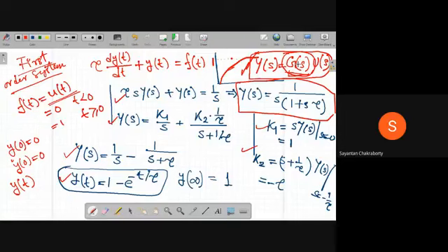So obviously this Ys will have two responses. One, the roots coming out of Gs, is called the unforced response or the natural response. And the other, the roots contributed by Us or the input function, is called the forced response. So using the transfer function, you can obtain the response of a system, which is a combination of the natural response and the forced response of the system, right?